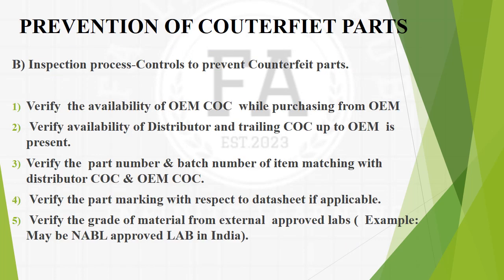Another control mechanism for counterfeit parts is the inspection process. During incoming inspection, if we have a good control mechanism, we can eliminate counterfeit parts. So one is to verify the availability of OEM COC while purchasing from OEM. If we are purchasing from OEM, original equipment manufacturer, we should ensure that we are getting OEM COC. The second one is to verify the availability of distributor and trailing COC up to OEM.